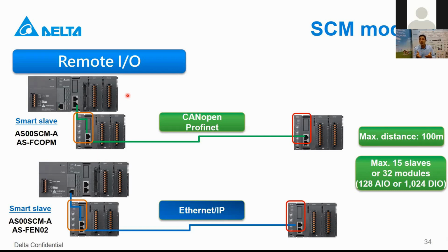So it is extra cost. Instead of that, you can make a small cabinet over there, and use this communication module only. This is not a logic control. This is just a communication module, and you mount the function cards or I/O points nearby it. Then make the wiring to these modules. The communication card will send the status of the points of the modules to the CPU directly.